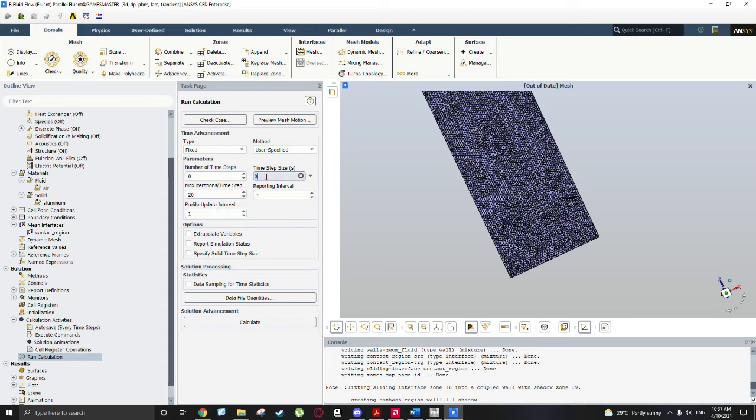So here, this is up to you: how many time steps you want, the time step size. I recommend a maximum of 0.5 second time step. That could be smaller, which would affect computational time as well, depending on how long a simulation you want. So at half a second, with number of time steps 100, we're going to get 50 seconds of data.